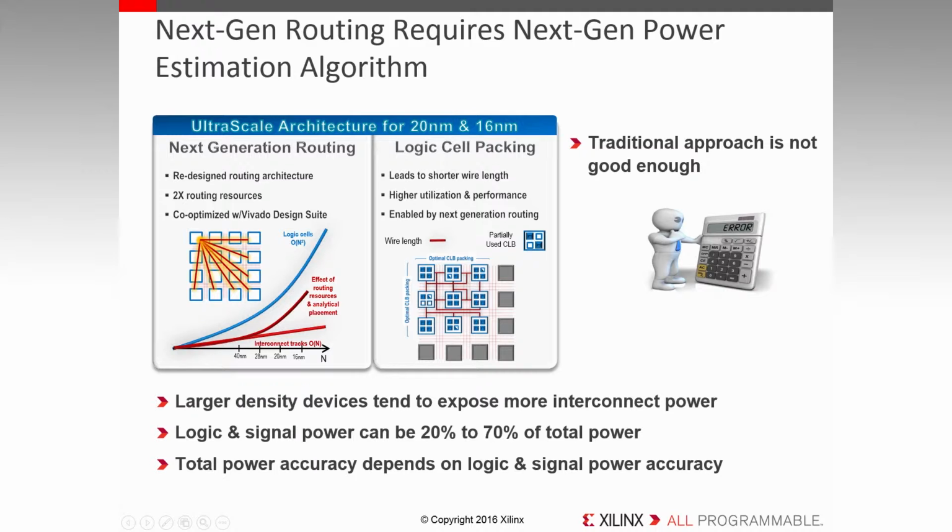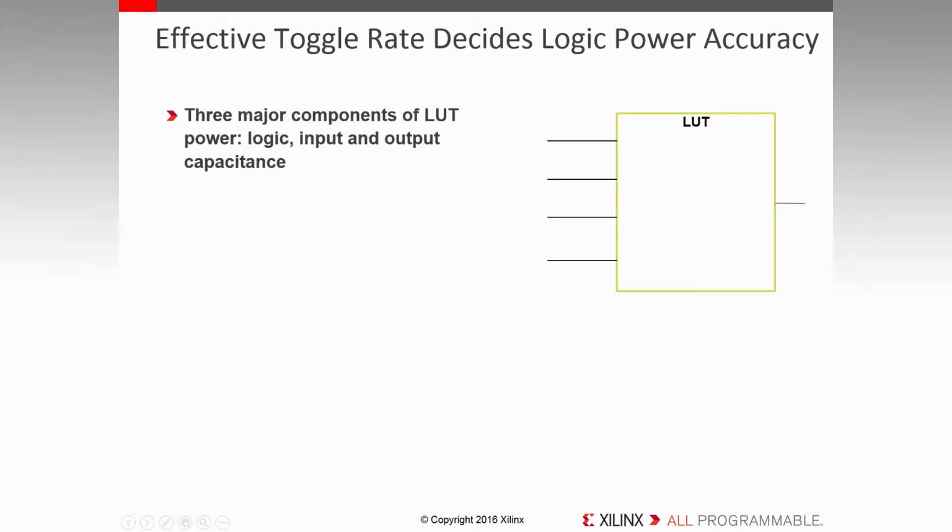Though Xilinx Power Estimator is a very abstract interface with minimal configuration settings, we constantly look for opportunities to improve the accuracy of power estimation, which helps our customers with early design strategies and decisions. As we know, device dynamic power purely depends on effective switching rate, which decides the number of times the node capacitors are charging and discharging during operation.